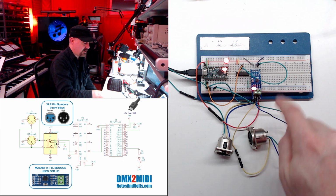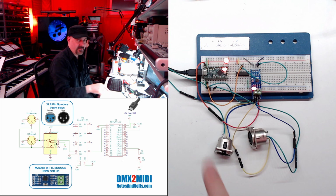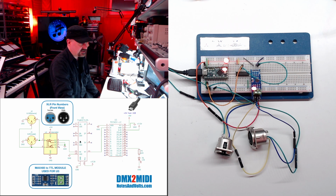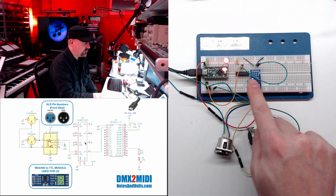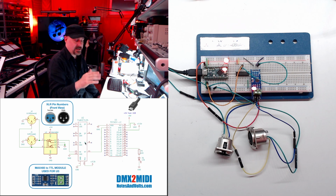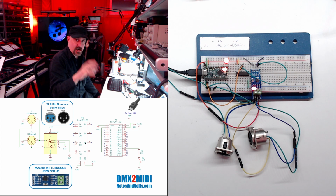So now we've got our messy DMX signal turned into a nice 0 and 5 volt logic level. Now remember, we said our Teensy board can't accept 5 volts, so we're going to have to condition that signal to get it in there safely. That is what this chip is going to do, and here it is on the board. This is called the 74AHCT125 chip, and this chip is called a quad buffer chip. What it normally does is take a low 3.3 volt signal and drive it up to 5 volts to run 5 volt logic. But we needed to do the opposite, which is to take our 5 volt signal and cut it down to a 3.3 volt signal.